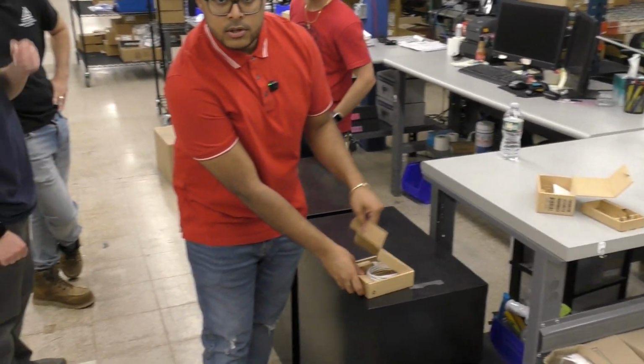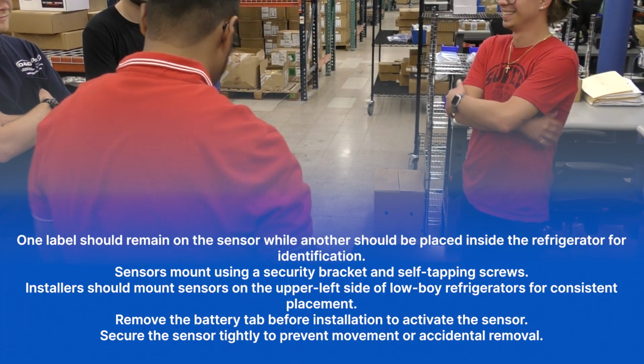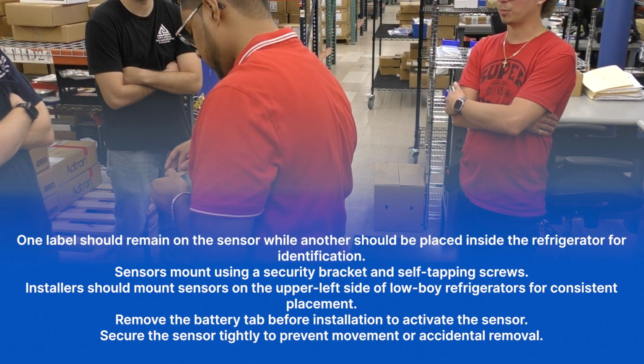Section 10. MT11 sensor installation. MT11 sensors include serial number labels that should be applied immediately during installation. One label should remain on the sensor, while another should be placed inside the refrigerator for identification. Sensors mount using a security bracket and self-tapping screws.